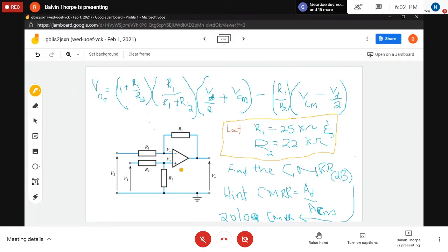Repeat that, sir? The common mode what? The common mode rejection ratio of an operational amplifier. Can anybody tell me what that is again? Yes, sir. It's 20 log the open loop gain over ACM. All right, you're giving me a formula. That's not what I want. I have it here now, if that's what you're trying to tell me, that this is your common mode rejection ratio in terms of a formula. But can you tell me in terms of words, what really is this formula saying?